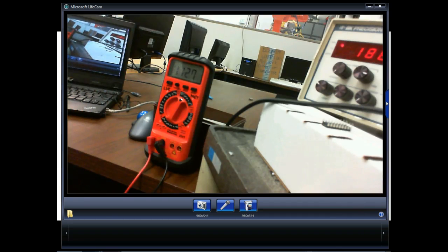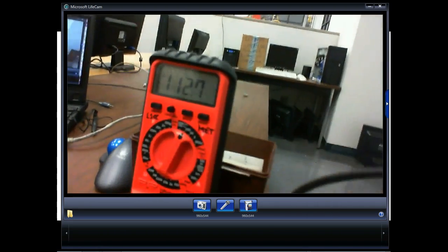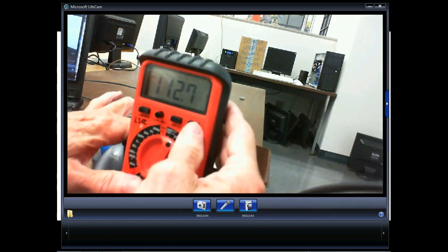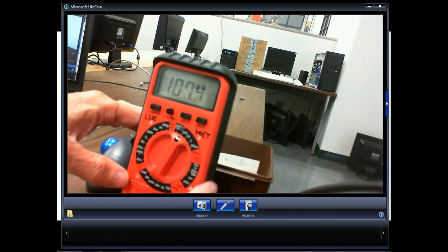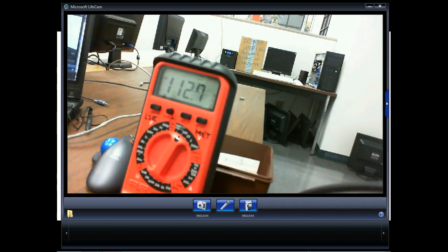And it's measuring what? Can y'all read that? So we have 112.5 volts AC. What's it going to measure when I switch my meter to DC? What does it measure? 0. What does it measure when I put it on AC? Well, there is not 0 volts there, right? You understand? This gets a lot of people hurt.